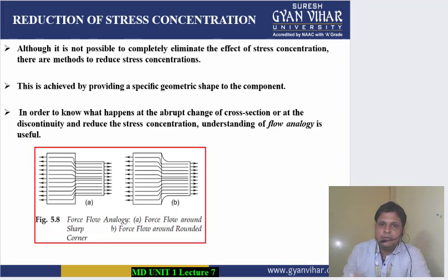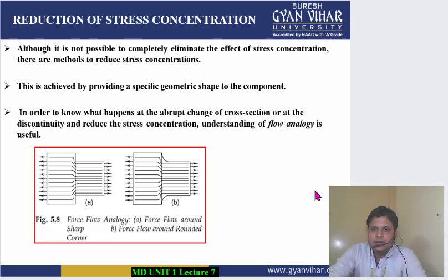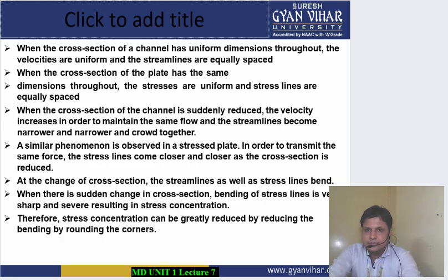We can smoothen the cross section. We can round the corners of the particular element where there is an increase in stress concentration. All right. So coming to the next one,